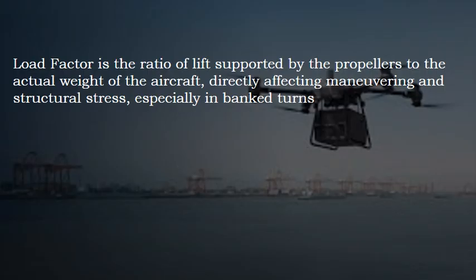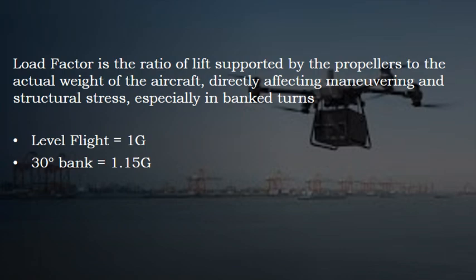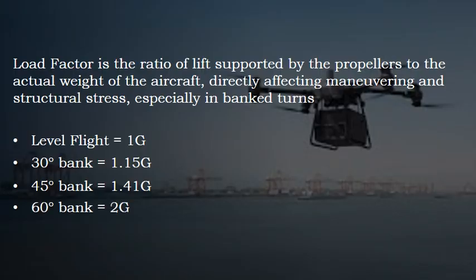Load factor effects can be quantified in the following way. A level flight has a 1g effect on the platform. When a drone makes a 30-degree bank, it increases to 1.15 Gs. A 45-degree bank has a 1.41 G effect. And a 60-degree bank has a 2G impact, essentially doubling the weight on the drone.